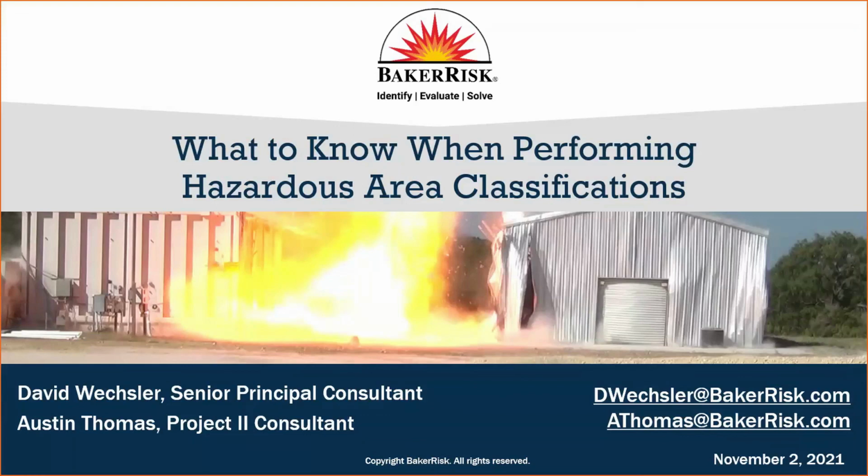If we assume that the roadways are not public roadways, but they're inside the plant boundaries, I would say yes, they do. Because we know if we have a source near a road, just because the road's there doesn't mean that the source or the footprint of that hazardous area classification will end at the road. It may go right across that road into the adjacent unit. It may also go across the fence line to the adjacent processing plant or other area.